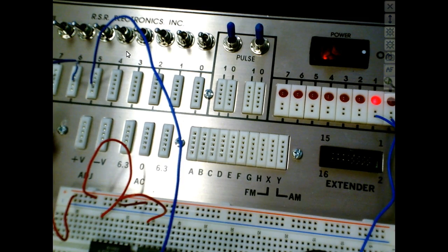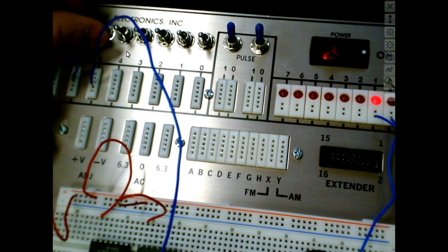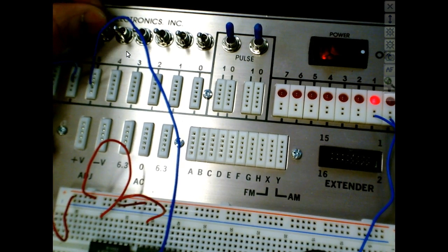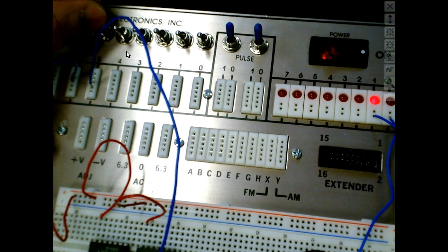So we started off and we said it was latched, right? You understand? And then from then on, we're controlling it. Everybody understand that? Okay, so I'm going to bring the set to a 1. That's what it says for next, right? No, I'm going to put 2 zeros and I'm going to clock it, and what did it do? It stayed set, right? But now we're controlling it. The first one we don't know. After that, we're controlling it, right? So it stayed a 1.